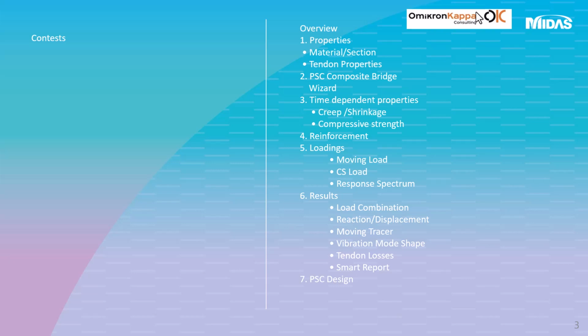Also loadings like moving loadings, construction stage loadings, and the response spectrum for the earthquake analysis. Then we'll see how we can check the results for the load combinations, reactions, moving tracer, vibration mode shape, tendon losses, and we'll see how we create the report. Also, we see how we create the PSC design.